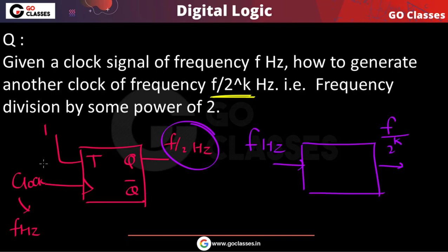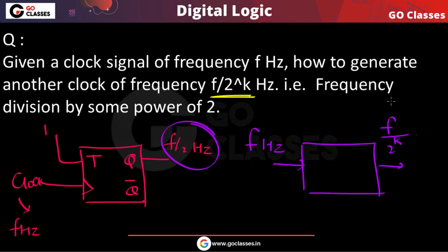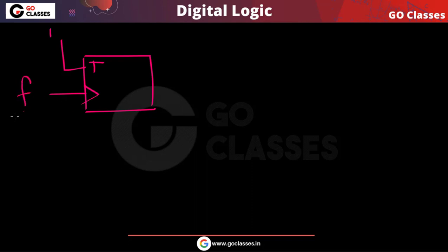Let us assume that you want to get a frequency of f by 2 power 2, basically f by 4. Then what to do? The idea is very simple. You already know that this is a T flip-flop, and this is your clock. Let's assume this clock has frequency f hertz. Now you know that this output will have f by 2 hertz frequency.